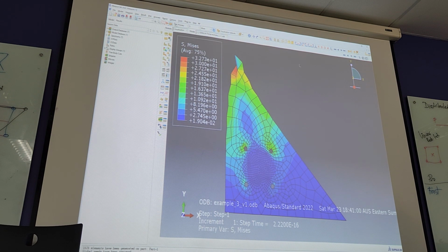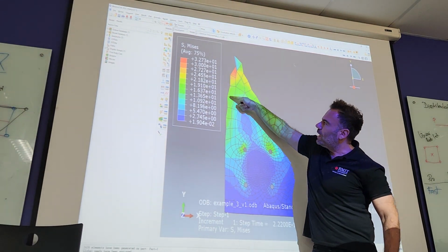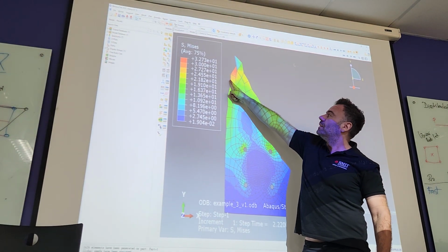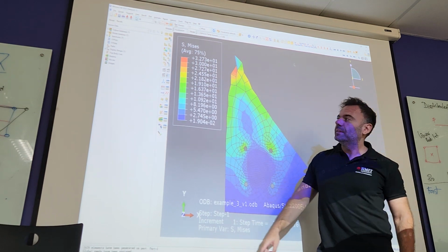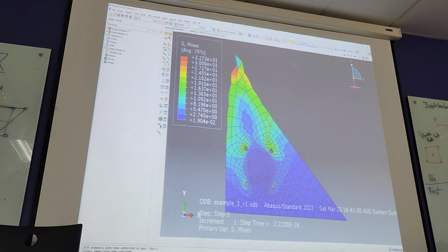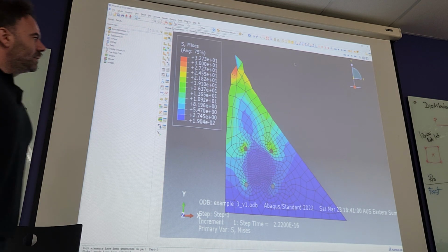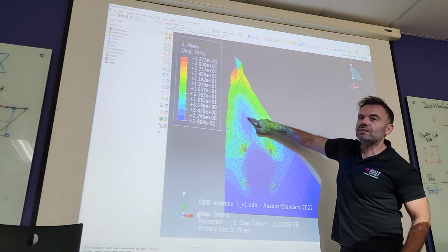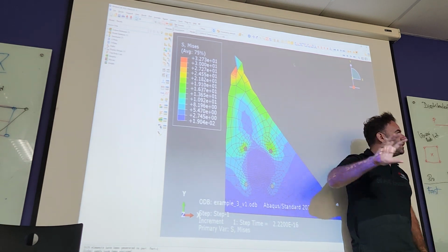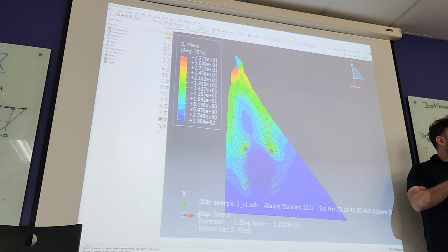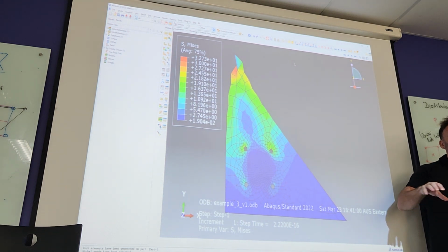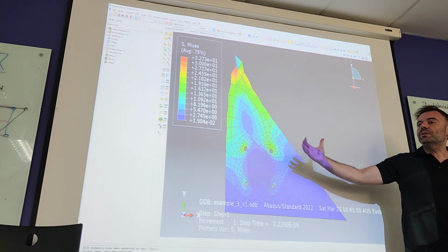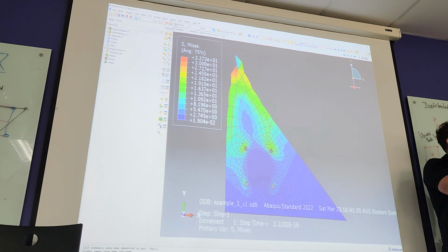Okay, this is a perfect example. You can see here the shape of hourglassing deformation. Yeah, that shape here. See, it's here, and gets propagated everywhere else. So this is evidence of hourglassing happening. Yeah? So, yes, this is an extreme case, but very often it could be visible.